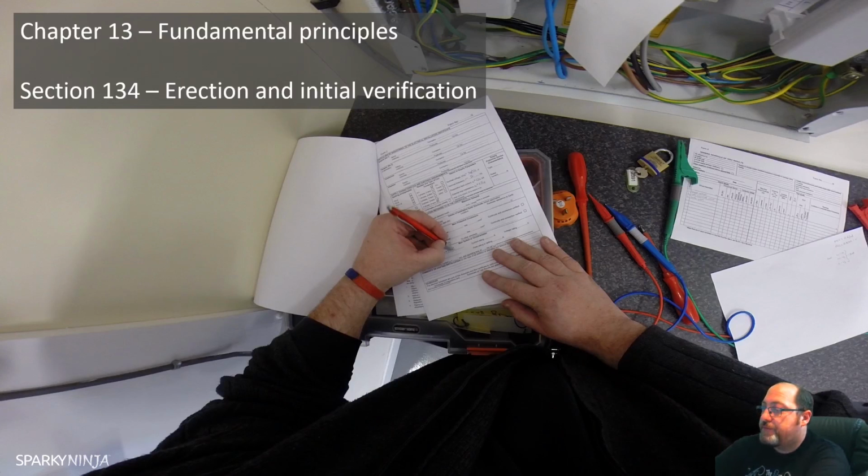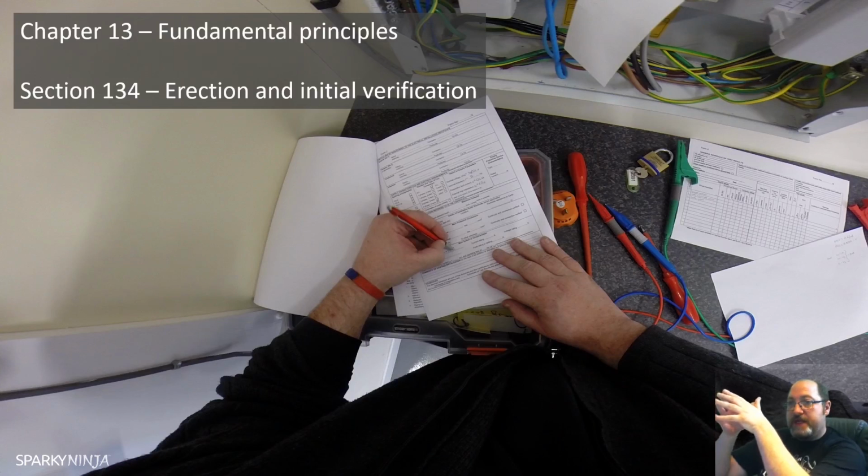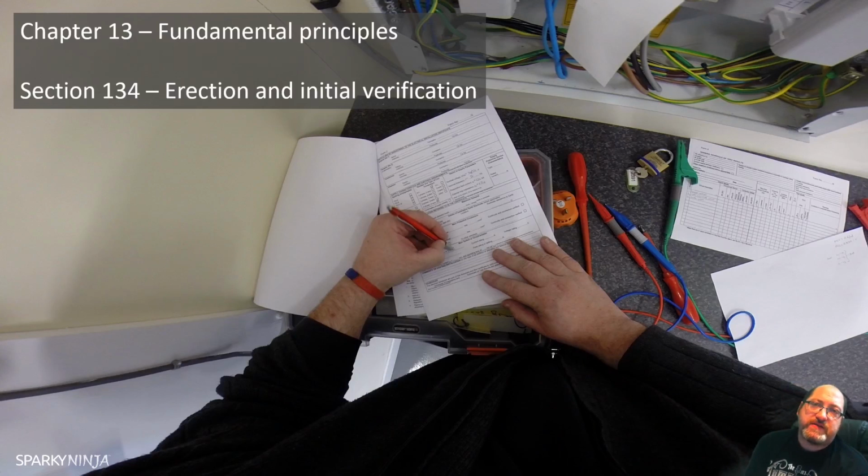We then have initial verification during erection and on completion of an installation or an addition or alteration to an installation, and before it's put into service, there'll be appropriate inspection and testing carried out by skilled persons competent to verify the requirements of this standard have been met. So a couple of things from that. You need to be skilled to know that the requirements of this section have been met. So you need to know the regulations, and you need to know the installations you are inspecting to understand the requirements of that. But you must also do it during the erection process.